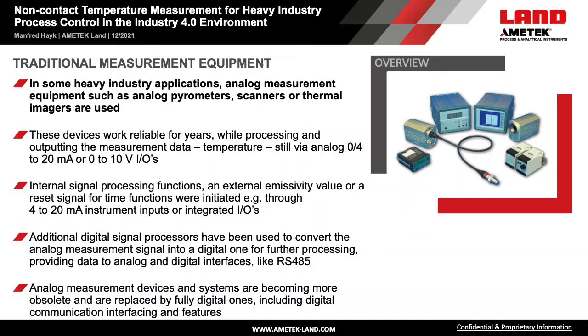Additional digital signal processors were used to convert the analog measurement signal into a digital one for further processing and providing the data to analog and digital interfaces like RS-485. Analog measurement devices and systems more and more get obsolete and are replaced by fully digital ones, including digital communication interfacing and features.